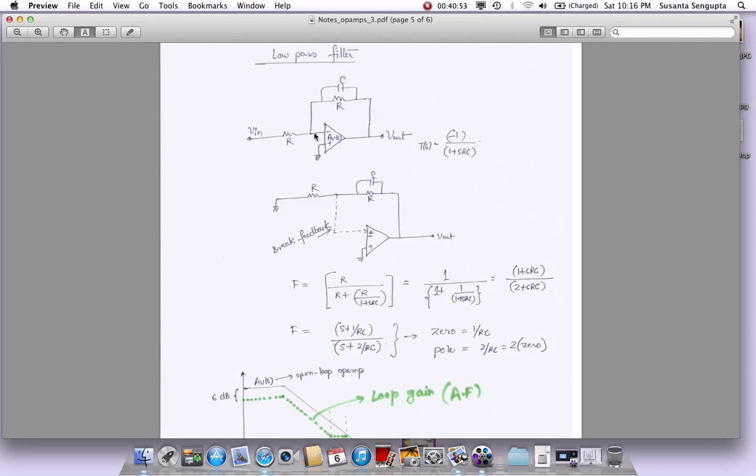This is very widely used in the RF world, where let's say you're designing a receiver. In the receiver, when you have the mixer and you down convert, after that you would actually have a stage like this, an op-amp RC stage, to do some filtering. Maybe not there, maybe further out, but in many applications the op-amp RC type filters are very widely used, and that's why I think this is important.